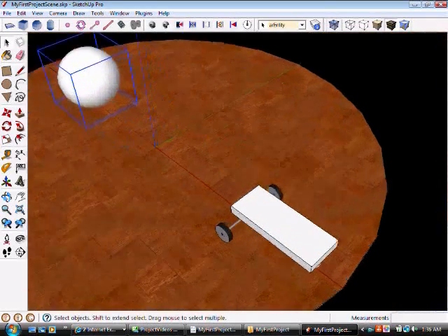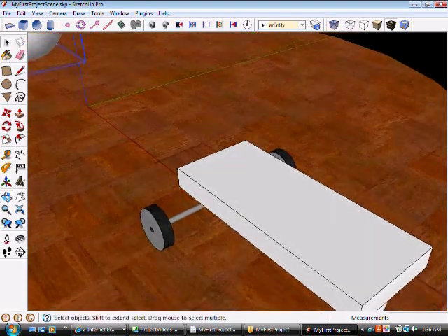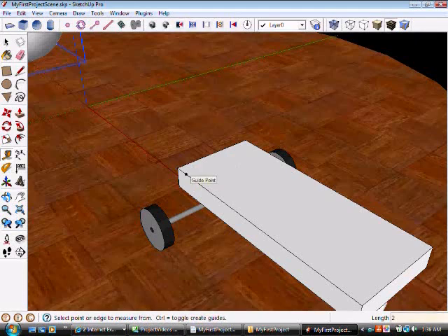Now let's go mount some light sensors on the differential drive. First, let's use a tape measure to figure out where to put it. Let's go back 2 inches, and then we'll go over 2 inches. Make it 1 inch. And on this side, back 2 and over 1.